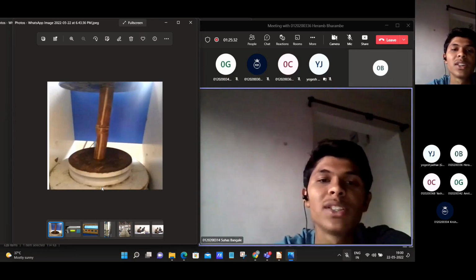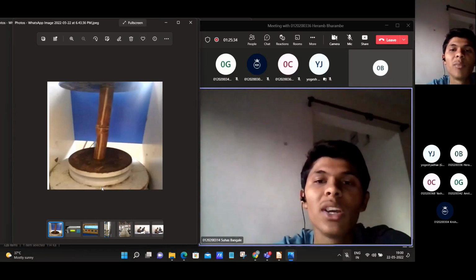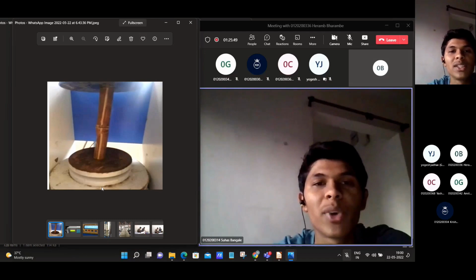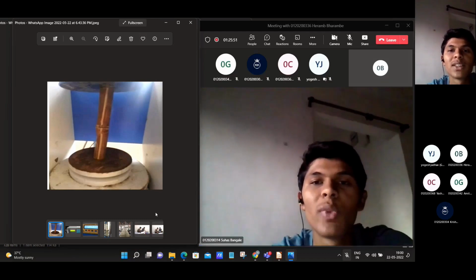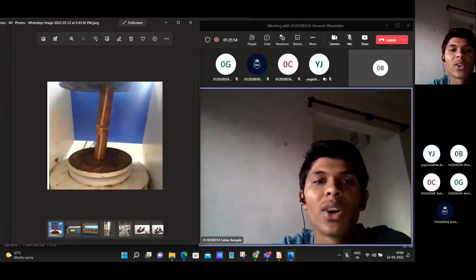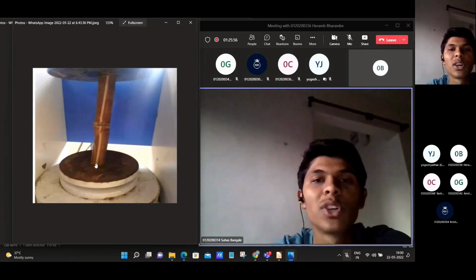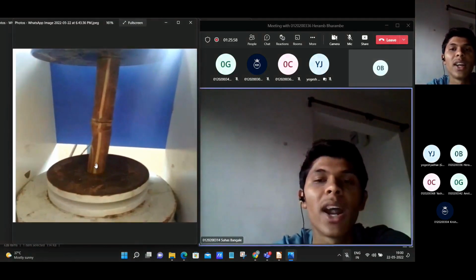Then there is a compressive test. In the compressive test, we compress the bamboo, applying opposing forces that push inward upon the specimen from opposite sides, otherwise called compressing, squashing or crushing force. The test sample is generally placed between two plates that distribute the applied load across the entire surface area of two opposite faces of the test sample, and then the plates are pushed together by a universal testing machine. You can see the picture of the machine.